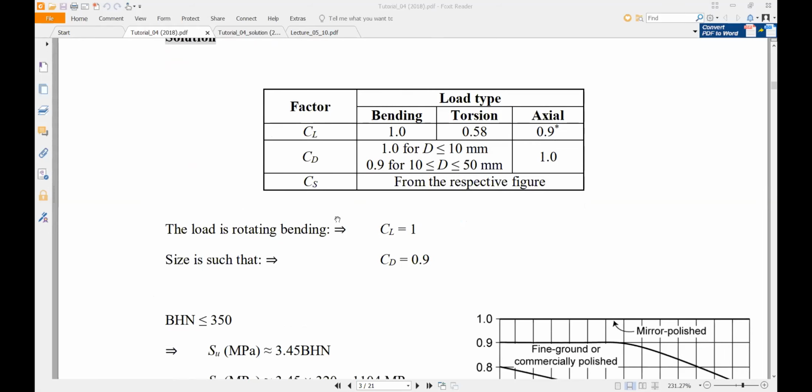So anyway, we need to calculate these things. So I'm not going to explain how we can. Yeah. So quick question for the tute. Will the exam style questions be similar to this, the format? Because for the tute question, first you find K, then you find the SN value, and then you find the allowable F for each of the fillets, and then one for the groove, and then you compare all of those, and based off that, you figure out which one will have the failure point.